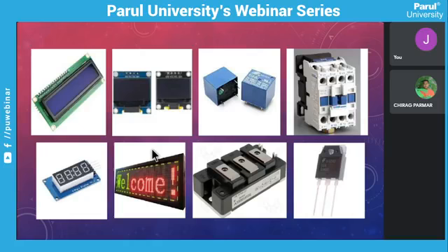It's an 8-bit serial in parallel out shift register. So an 8-bit data comes in, and it controls 8 LEDs. For another 8 LEDs, another shift register is applied, and for another 8 LEDs, another shift register, and that's how the array continues. All of those shift registers use just 3 lines to get the data from the controller. So even a small controller can control the display of such size. It just uses 3 pins, and all of the remaining work is done by the shift registers. It keeps shifting the display, and that's how we see a scrolling pattern. So that's the working of the dot matrix display.